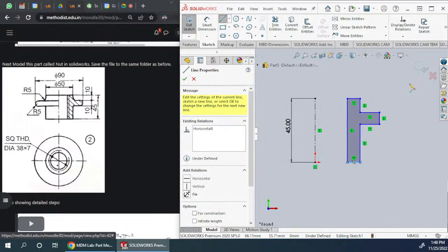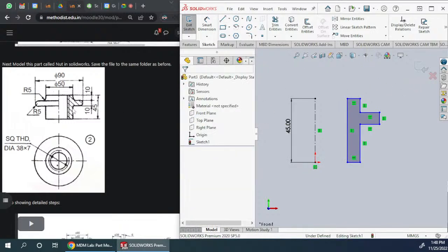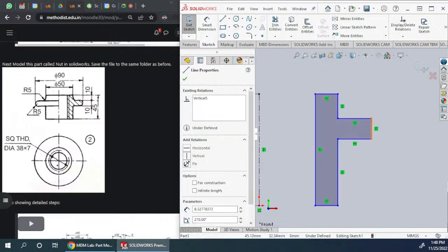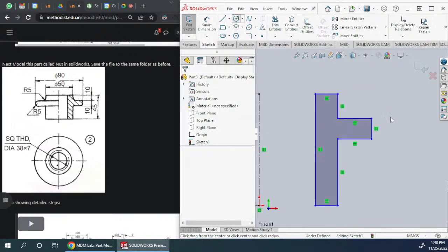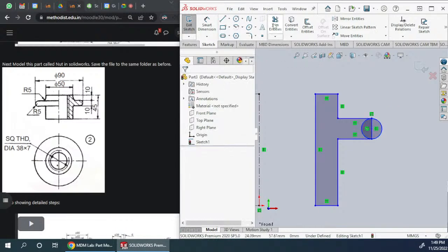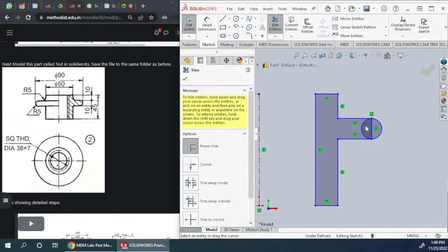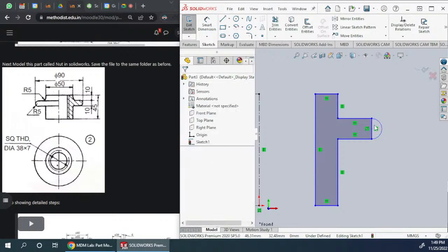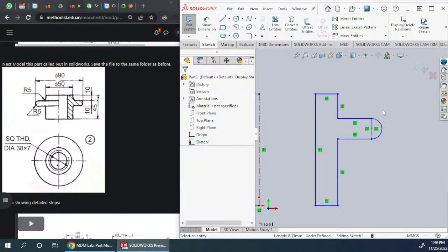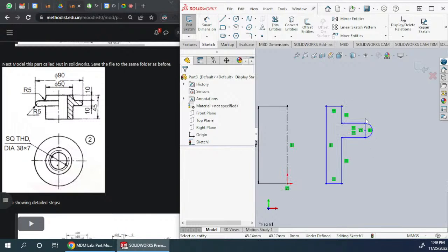Over. So now here there is a round. This part is round, right? So let me create this round. How to create a round? You can take a circle, keep it from the midpoint till the top point. Use the trim command to remove only the inside part. Don't remove the line. If you remove the line, there will be other problems. So this line, you should convert to a construction line. Fine. So now we have the closed geometry.